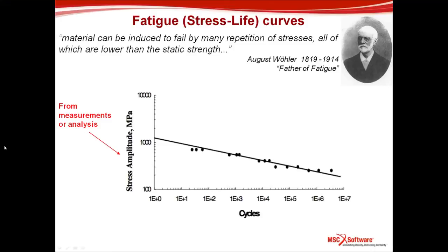Over the years, of course, there have been lots of development, research, and scientists all applied to the topic of fatigue, but the fundamental proposition still remains the necessity of an empirical relationship between the applied fluctuating cycles of stress and the repeats that can be obtained through these cycles. So this is nicely represented by the stress life curves, which is quite often associated to fatigue analysis.